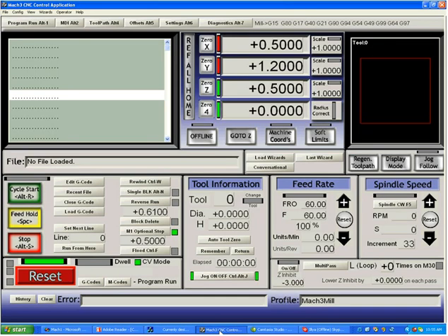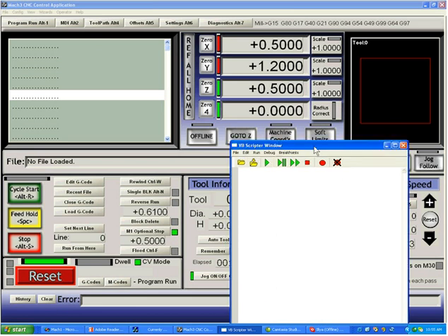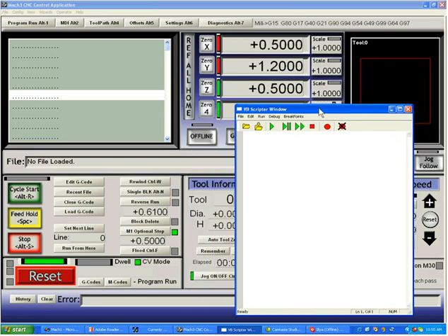And let's go back to Mach 3. In Mach 3, we have under the Operator menu a Visual Basic script editor. Let's pull it up so we can see what it does. Now, this is just a small text editor, and it allows us to open scripts, close them, save them, single step through them. Let's write a very quick program where we say we want a variable called x, and we want that variable to be the value of getUserDRO 1200.